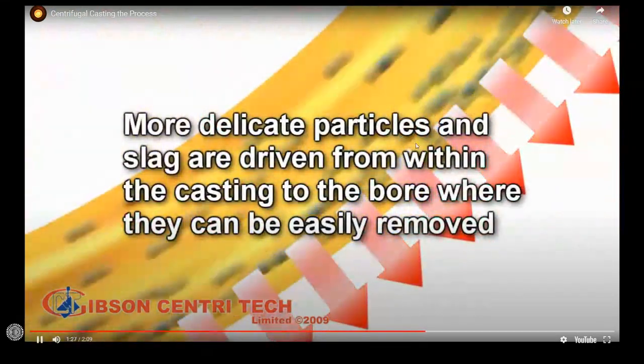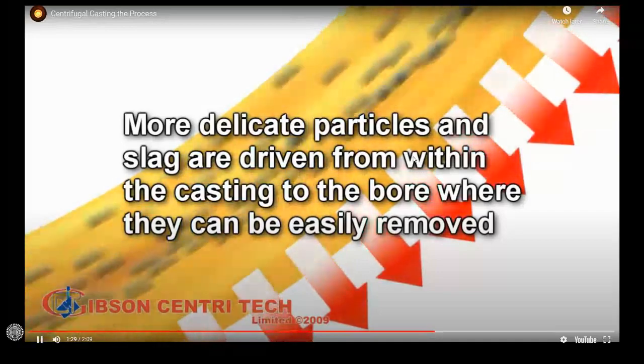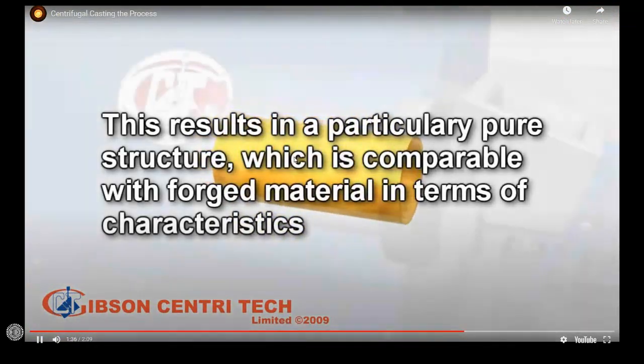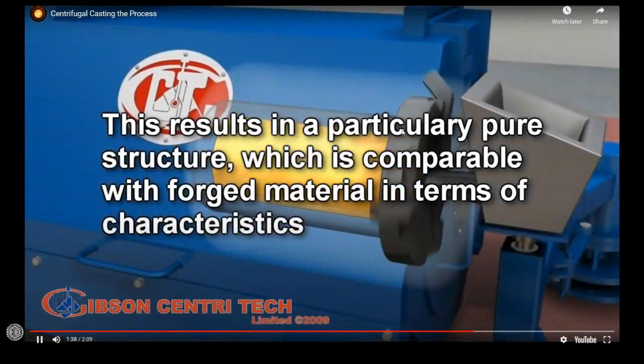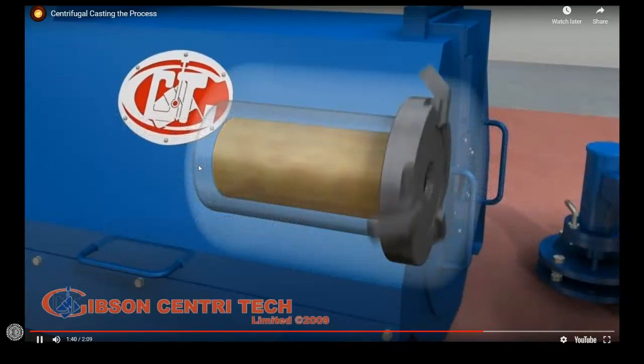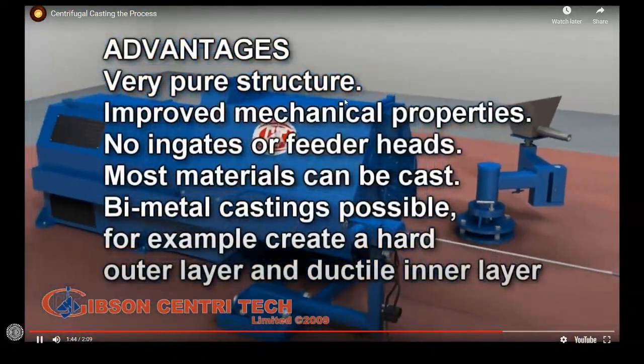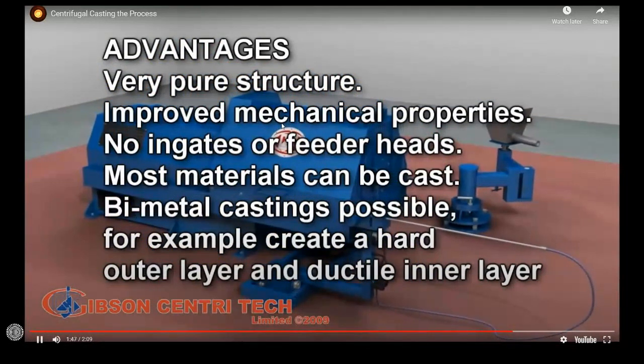And because of that centrifugal process, the heavier or the more dense materials will go to the outside. That's the metal. The less dense material is the slag. And machine that off, this gives you a very pure metal structure. So the advantage is a very pure structure. That gives you better mechanical properties.